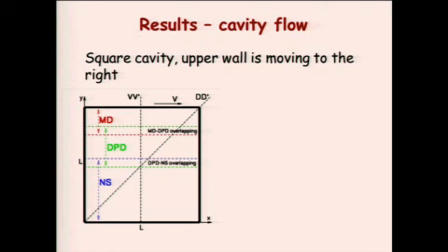Now the problem for the Navier-Stokes equations here is that at these points where the stationary walls meet the moving plate, there is a singularity in the solution which is not integrable, which means if you have a finite difference method and you keep refining your mesh, you're going to run out of digits in your computer because the numbers there are going to get so large that you won't be able to handle it.